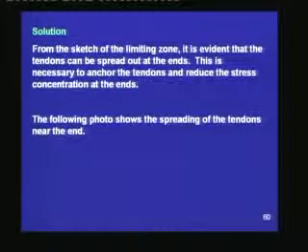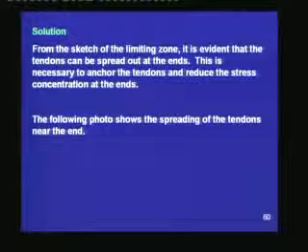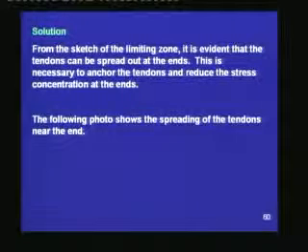From the sketch of the limiting zone, it is evident that the tendons can be spread out at the ends. This is necessary to anchor the tendons and reduce the stress concentration at the ends. The following photo shows the spreading of the tendons near the end.